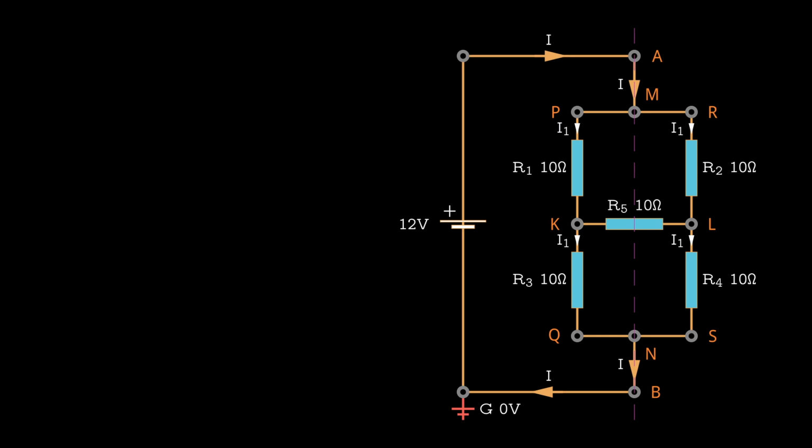To simplify, we trace the circuit starting from point A. As we move, if we encounter a resistor, we cross to the other side and assign a voltage. If we come to a node with branches, we check if the branches have the same number of resistors in series on both sides. In this diagram, there are two branches with identical resistors on either side of the dividing line. As we continue along the resistors, we eventually reach a node with equal voltages. Mark these voltages as V1.